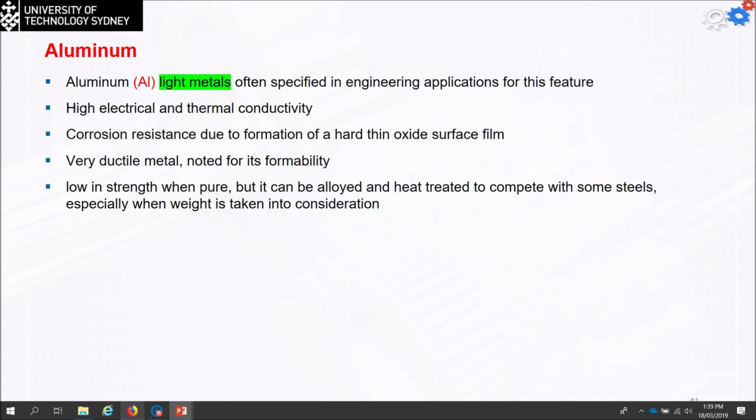Now, a very important thing, even when we work in the future, is the oxidization layer at the top surface of the aluminum. Usually, if you scratch any aluminum surface and come back after 2 days, you will see that the color has changed to be the same as the old color. It oxidizes very fast, but we don't want to oxidize it further. So usually when they do the casting for aluminum, they try to keep the oxidized layer on the top, so we're not going to oxidize more layers of the metal when you do the casting.